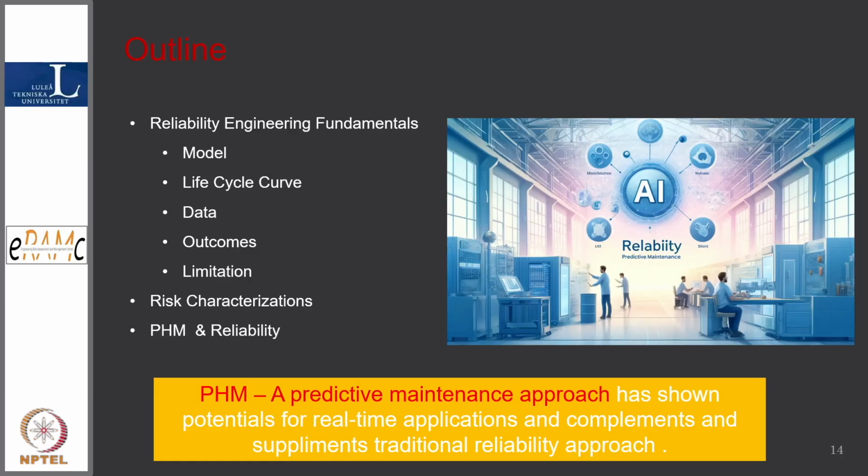Okay, and then we know that PHM is a predictive methodology, and reliability fundamentals do form part of it. It is not totally done away with, because if I have to estimate the uncertainty, I need a distribution. Distribution is an inherent component of reliability engineering. But then the main driver is degradation, and based on the degradation, the evaluation of remaining useful life.